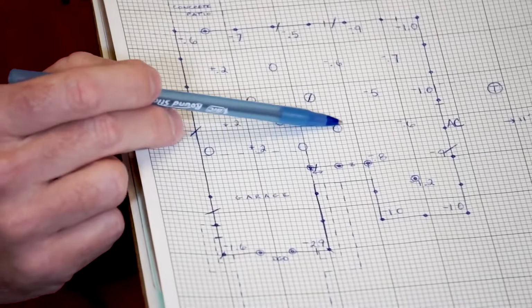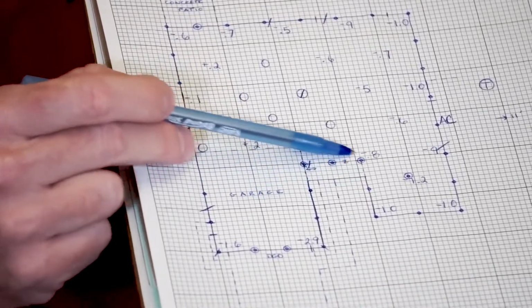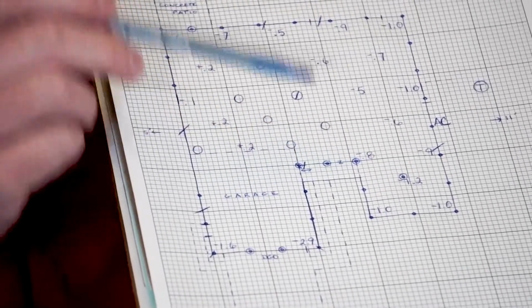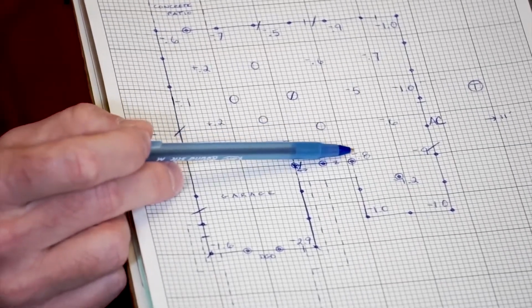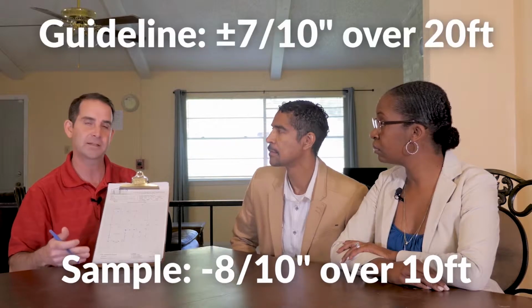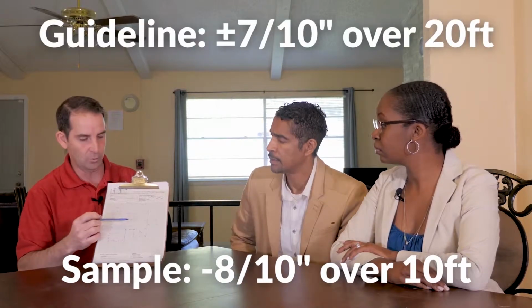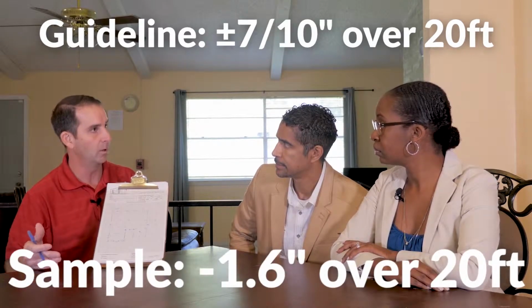And I'm gonna take an easy example here. I'm gonna say from this point right here, which measures 0, to this point right here in the corner, this will be our front porch area. So this is the corner of the front porch inside. We measure -0.8. So this distance from this 0 to -0.8, or 0.8 of an inch low, is about 10 feet. Okay, our guideline is 7/10 over 20. So if I double this to make it 20, that means I'm 1.6 inches low over 20 feet. And so you can see that that's more than double the guideline of 7/10 over 20 feet. So that's how that works.